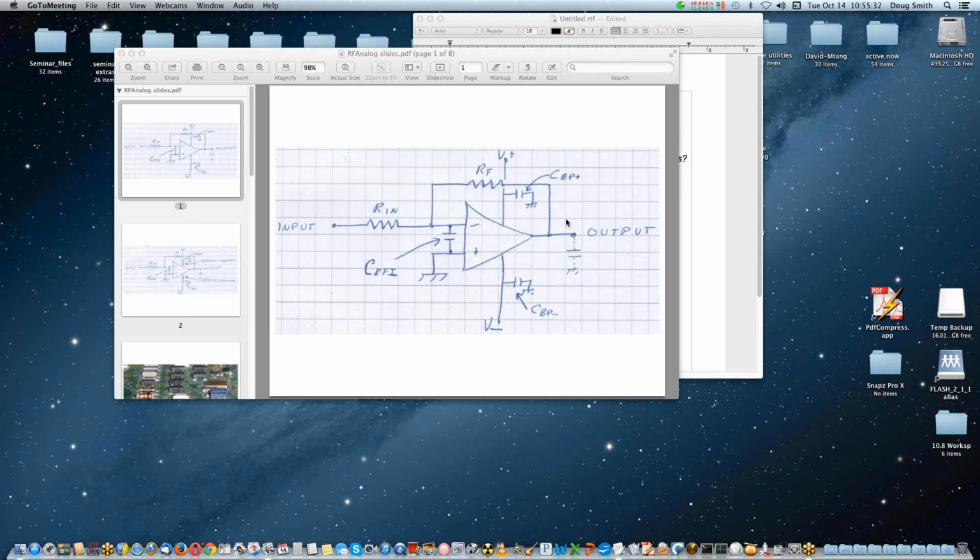Okay, guys, we only have 5 minutes left, so we're just going to ask one more question. Layout or traces affects the susceptibility of the circuit. Aside from adding capacitors as mentioned, what other solutions do you recommend? Short connections. Yeah. If you mount the thing over a ground plane, a multi-layer board, then that's sort of good because it helps to cut down the loops for RF purposes. You just have to make sure that you've accounted for any capacitance to the ground plane that's affecting the operation of the circuit.